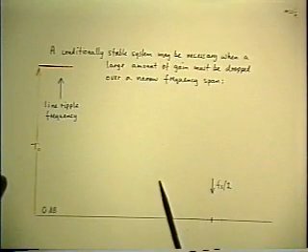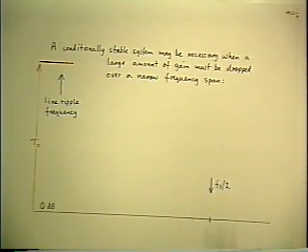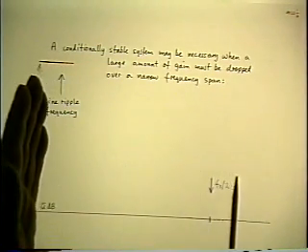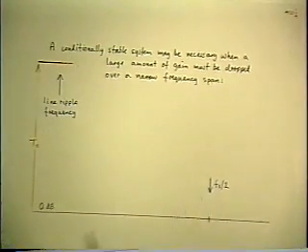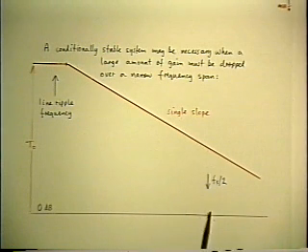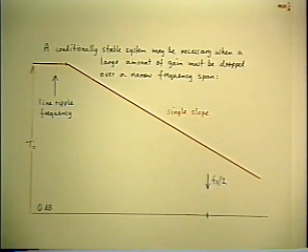Anyway, back to the audio amplifier, or whatever the application is, the design actually imposes a window, a certain frequency range over which you have to get rid of all the loop gain. And if you do it with a single pole, you don't make it. You don't fit in the window.